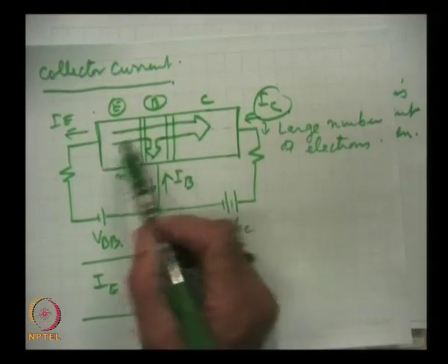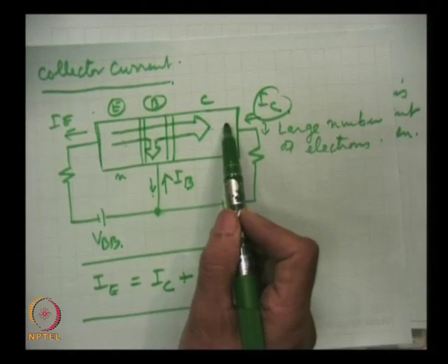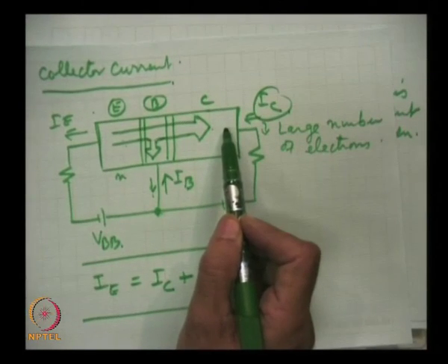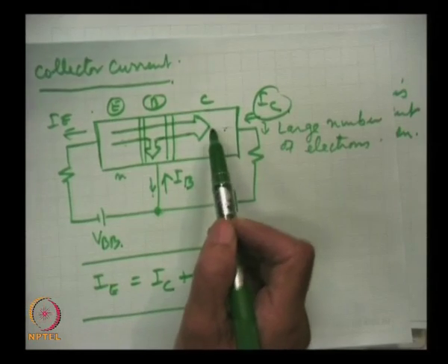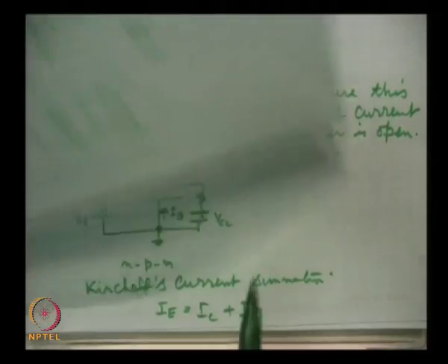The only difference is that when we go on increasing the frequency, the NPN transistor will function better and maintain its performance up to a higher frequency. You can see here that in an NPN transistor it is all the role of electrons, and electrons have higher mobility, and therefore they can respond up to higher frequency.